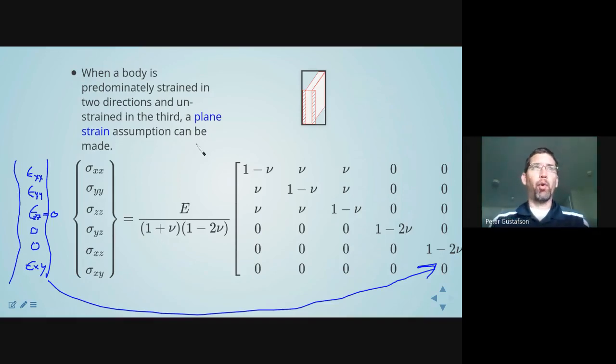It's also important to recognize that if you're doing something like finite element modeling, if you're running a two-dimensional model of a three-dimensional problem, you're going to end up choosing one of these two, plane stress or plane strain, as a consequence of modeling that structure as a two-dimensional structure. So when in doubt, use three-dimensional structures. When you can simplify it greatly and get away with using two-dimensional structures, wonderful. But then you have to decide, well, is it more like plane stress or more like plane strain?